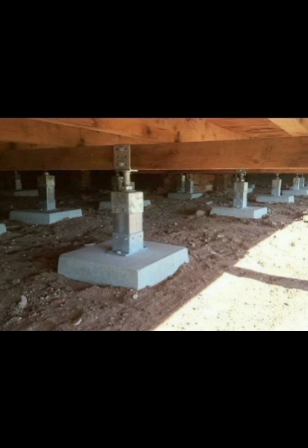First of all, a hole is drilled, or they dig a hole at a required depth, and then the piers are constructed by pouring concrete or laying the masonry into those holes. The piers are often spaced apart and connected by a beam to support the load of the structure.